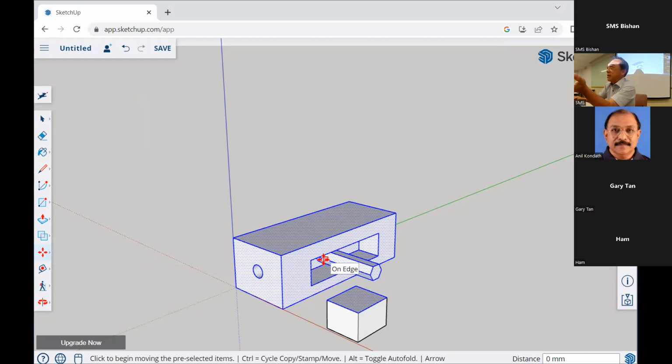So you have this problem. But sometimes this is a good feature to have. But if it's a separate object and you don't want that, one way to solve this problem is to click Control Shift and then unselect all the surfaces, including the four lines plus the surface. Then you click this button, then you can shift.